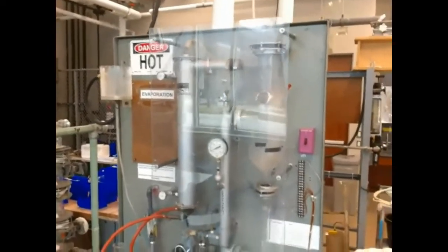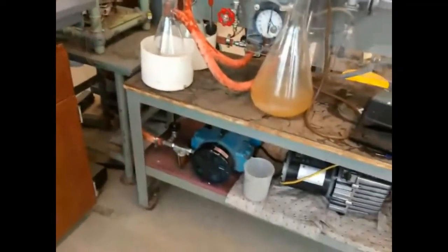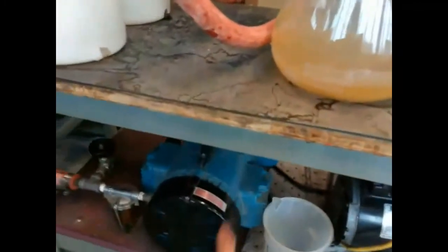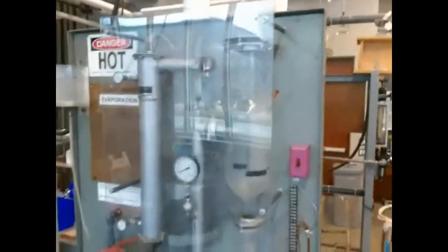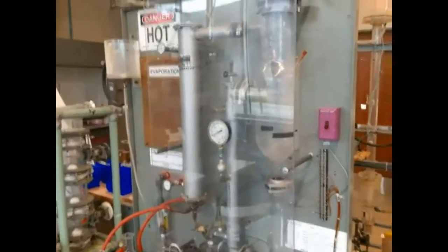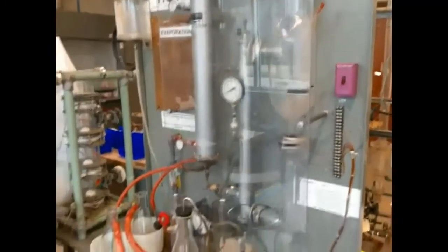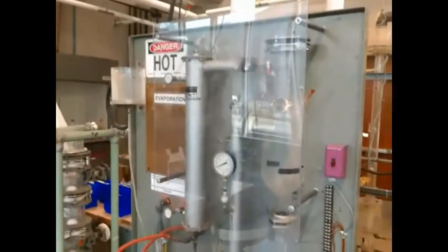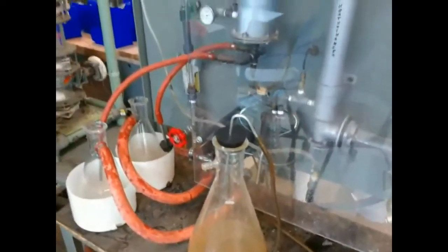So what we can do is use an evaporator where we use a pump here, a vacuum pump, this blue pump over here. It provides a vacuum on the system. So we load up our orange juice, or in this case, our sugar water. The vacuum applies a lower pressure. Lower pressure means a lower boiling point. So now we can boil at a lower temperature, and then our solution doesn't degrade. So this is a process where the students boil the water out of the sugar water. They collect it in these little flasks, these Erlenmeyer flasks, and then they get the process parameters out of it.